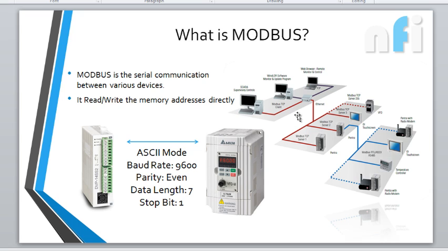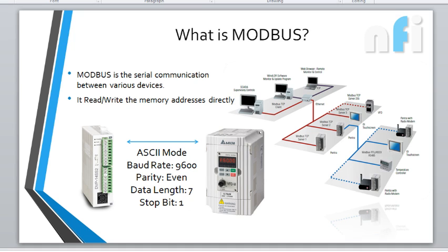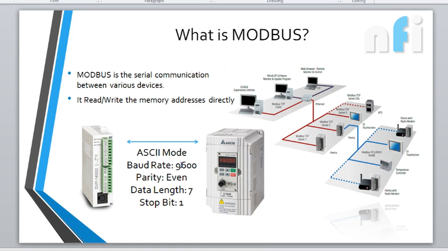Now we are not communicating via some voltage or current, as we do in a VFD, where we convert 0 to 10 volts into 0 to 50 Hertz, which is converted into frequency. So we use a potentiometer to change the frequency. Now suppose you do not want a potentiometer, and you want that thing to be done by directly accessing the memories, that is Modbus. Right?